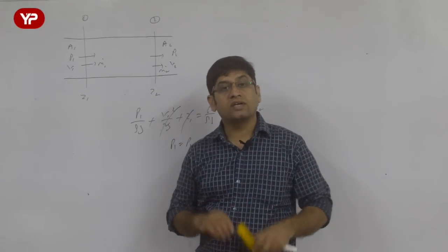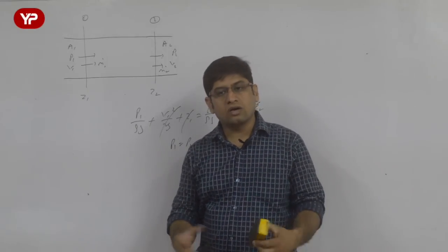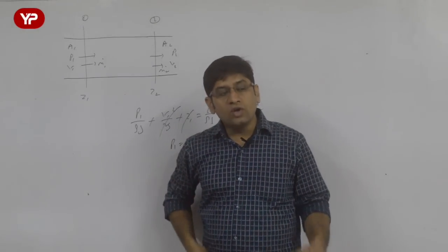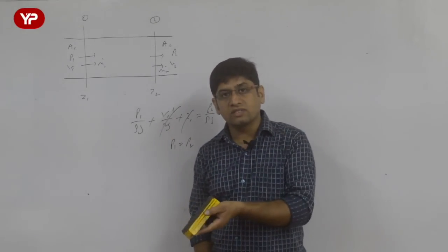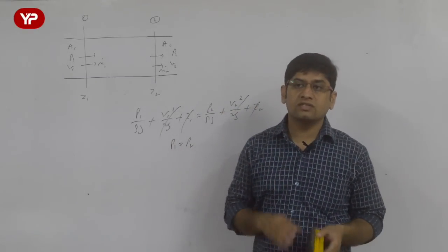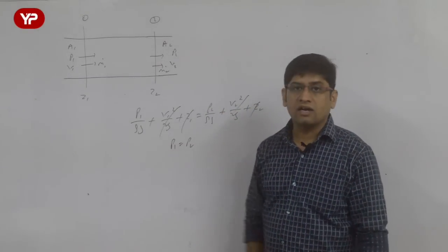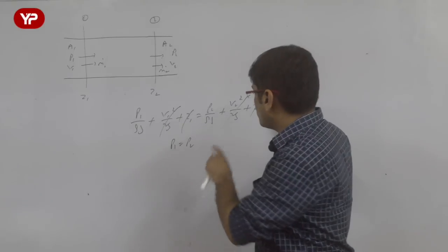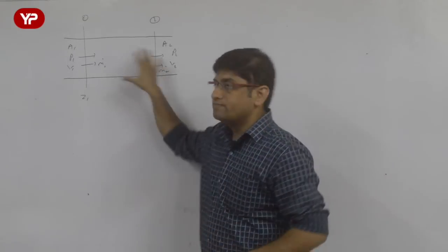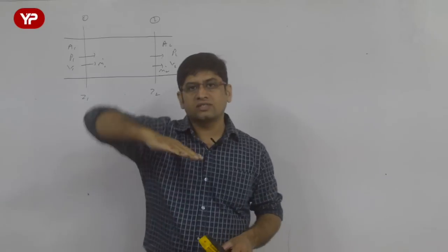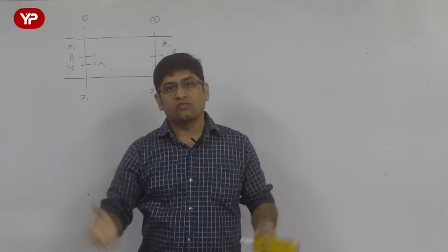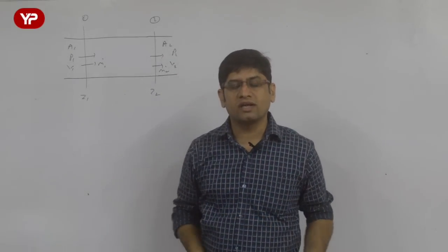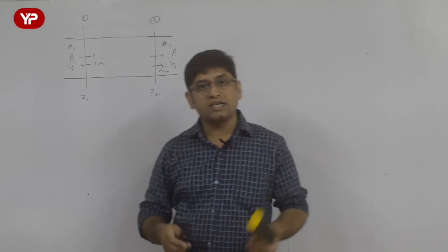Now the question is, if the datum is the same at the two sections, and if the pressure is also the same at the two sections, the fluid is made to flow either by datum difference, that is the gravitational potential, or by pressure difference or pressure gradient. Neither is there a pressure gradient nor is there a datum potential. How is the fluid flowing then? He is going to ask you this question. You understood my question? I am saying that fluid is flowing. Z1 is equal to Z2, that means the datum difference is not there, so the fluid is not made to flow through gravitational potential. But P1 is also coming equal to P2, that means there is no pressure gradient also. Then what is making the fluid flow? What is the dynamics behind that?